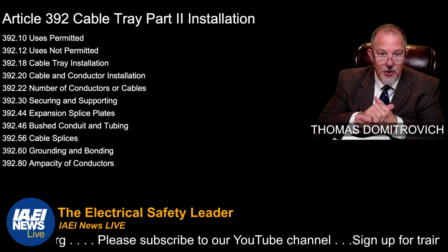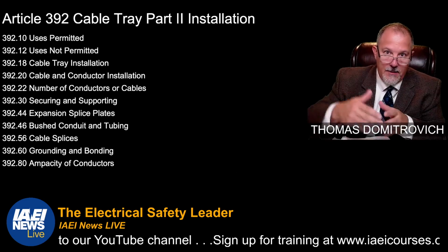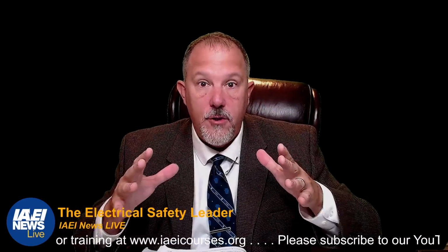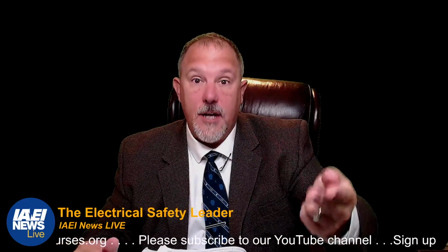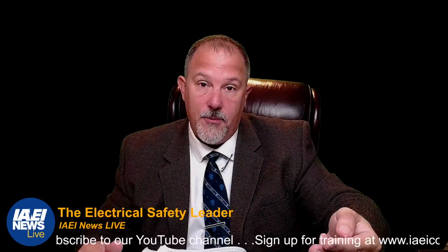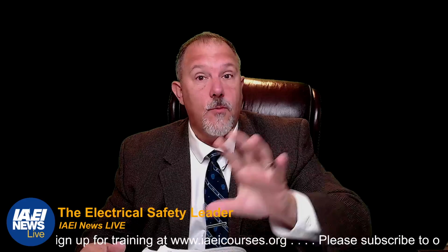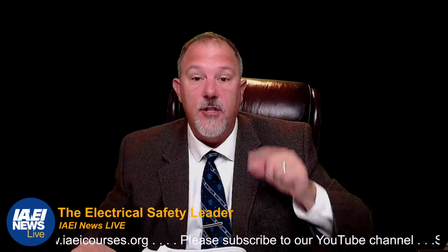Bushed conduit and tubing. So you've got to be careful on how you get conductors into the cable tray. You have to think about how you're going to mount your cable tray. You've got to think about what's going to go in the cable tray, the conductors. You have to think about how you're going to get those conductors into the cable tray. You don't want to void the UL listing. You don't want to compromise the integrity of the tray itself by cutting holes in the wrong locations. Follow manufacturer's instructions. Always follow manufacturer's instructions.